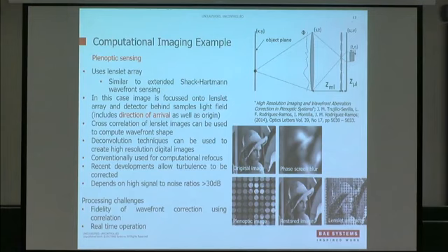But it does depend. What you're doing at the right-hand side is you're separating the light that would normally be focused onto one or two pixels onto many pixels, and the noise stays the same in the receiver. So it does need high signal to noise, or otherwise it won't work, because you'll just lose the signal in the noise on the receiver. And there are some examples here. I think they're simulated again. You've got the original image, they've simulated a blur, they've taken a plenoptic image, and they've restored it. The one on the right is just because the restoration they used circular lenses, and the impact of that was there were bits that were blind, but there are ways to overcome that through using more rectangular lenses.